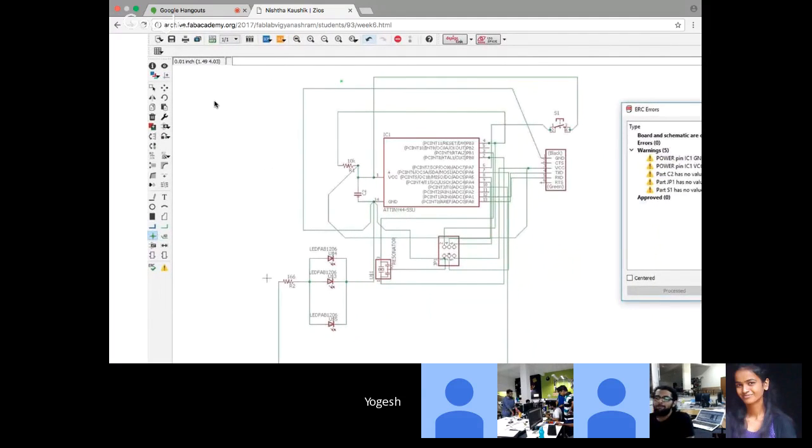Okay, it's simple. You switch back to your schematic, click on the command, and then double click on the wire. Consider that you're clicking on this wire, which is going from R1 10K to the PB3 of this IC, Tiny 44. Double click on this wire with the show command, and it will highlight this pin and the resistor's pin, so it will show that it's connected.